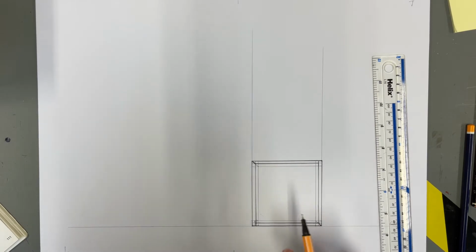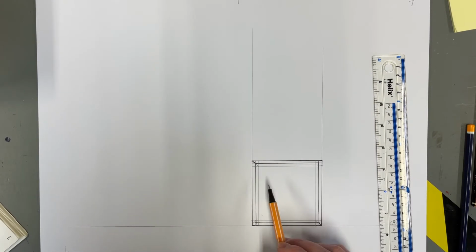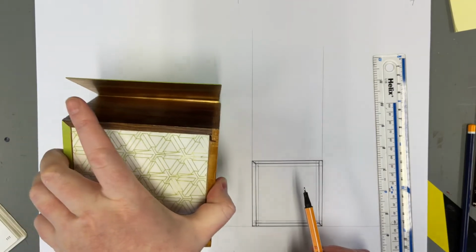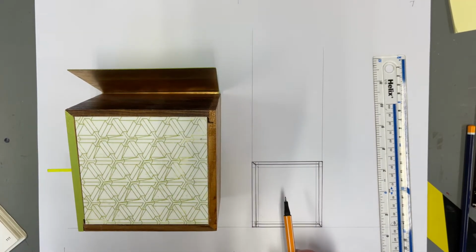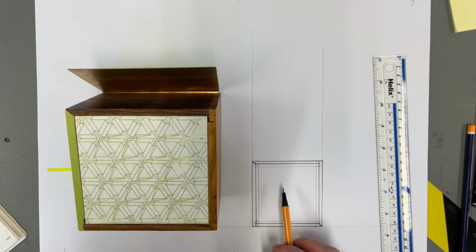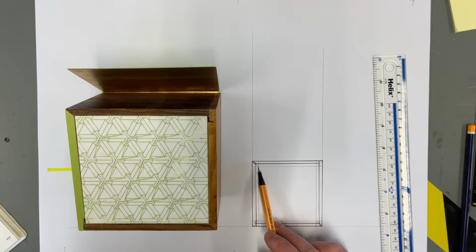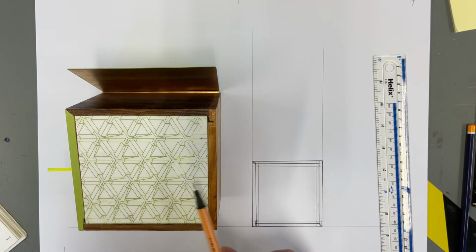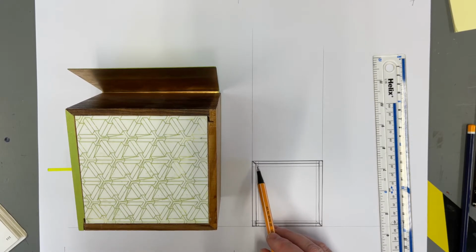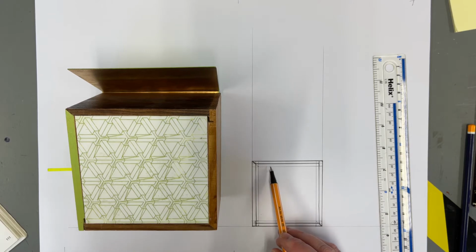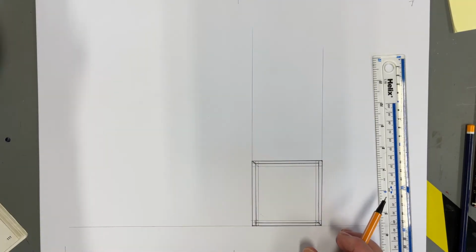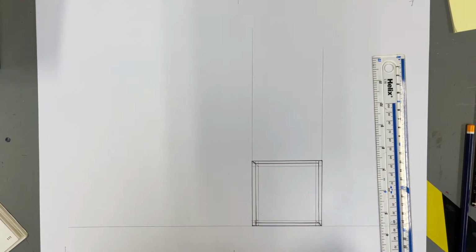Right, next thing, we can't see the hidden detail lines on the inside of the wood, but we still have to show the manufacturer that they're there. Now, we do have those as construction lines, so imagine that the piece of plastic was glass. Imagine we could see through that. Now, we would just about make out the rest of the mitre line here. We would then see the inside of the carcass, 12 millimeters thick, coming all the way around. So to show that in hidden detail, you would do this just as heavily as the outlines.